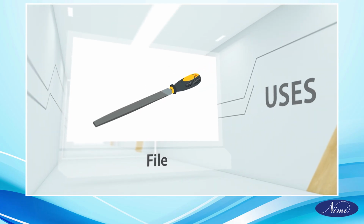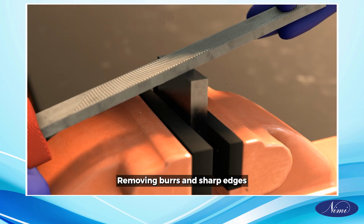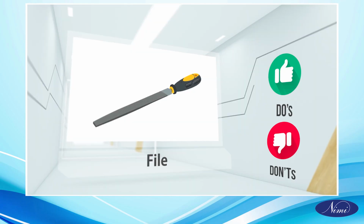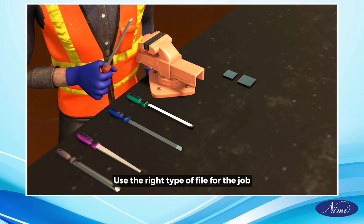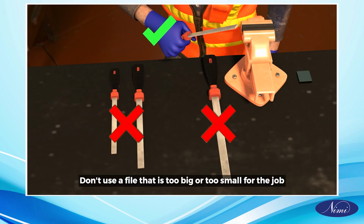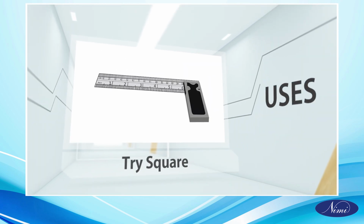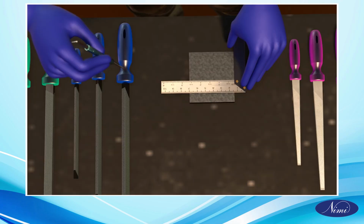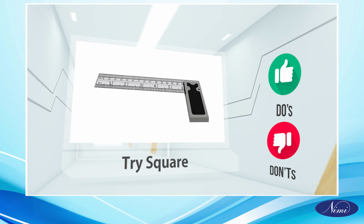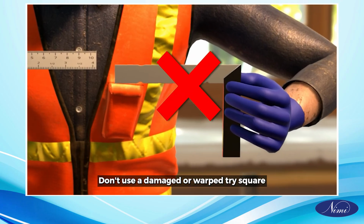File uses: smoothing and shaping metal surfaces, removing burrs and sharp edges, fitting and finishing. Do's and don'ts: use the right type of file for the job. Don't use a file that is too big or too small for the job. Tri-square uses: checking for squareness, marking right angles, measuring and marking. Do's and don'ts: keep the tri-square clean and dry. Don't use a damaged or warped tri-square.